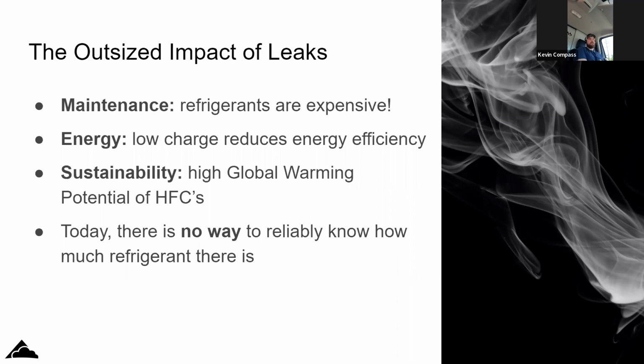I generally follow a routine. If I can't find it the first go around, I'll shut off the rack and let it build up pressure, and then I'll leak check it. Let the suction side come up, or start throwing things in hot gas defrost if they're in hot gas defrost. I've seen it where you could barely pick up a leak on a suction line, and then it goes into defrost and it's spraying out refrigerant.